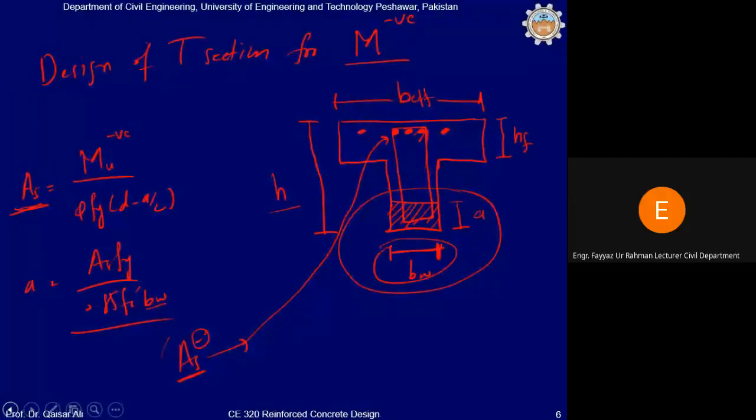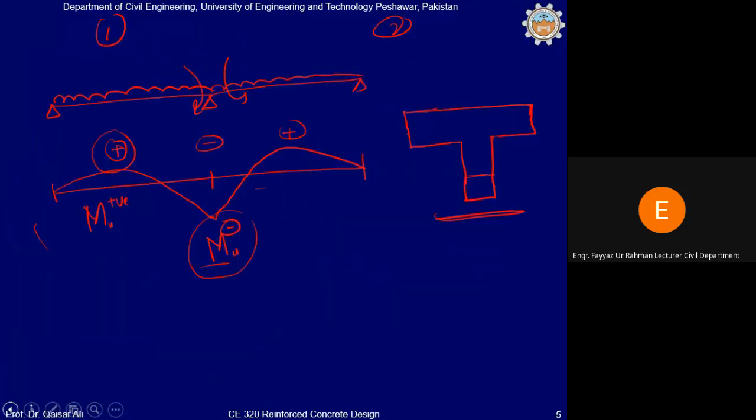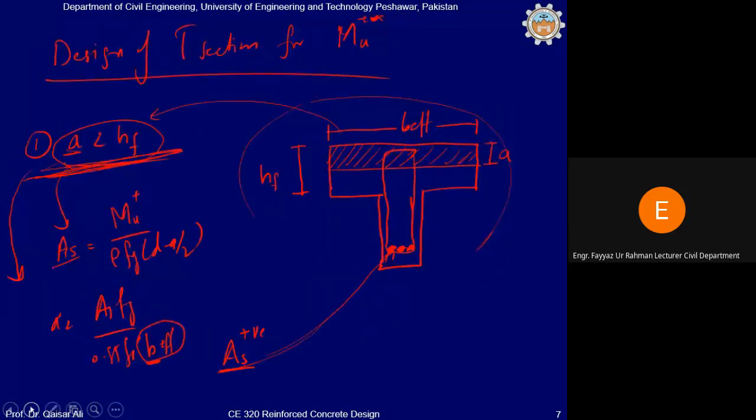अच्छा, these bars will be provided only at the interior support because there will be negative moment at the interior support. और जो bottom bars हैं for positive reinforcement, those will be provided in the bottom reinforcement, and you can curtail some of the bars at the interior support. Clear? वो आगे हम पढ़ेंगे. सही. ओके सर.